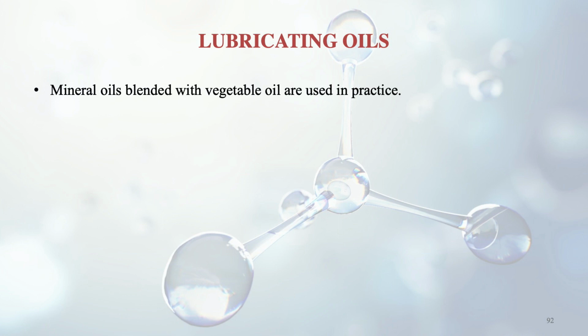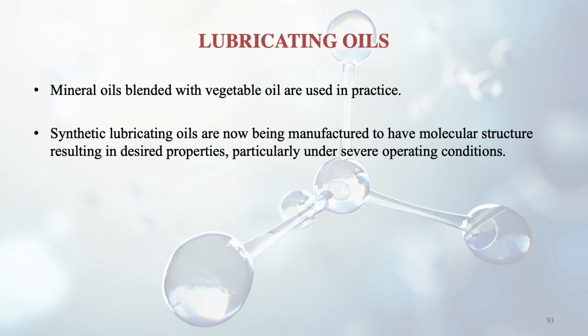Mineral oils blended with vegetable oils are generally used in practice. So we are using the combination of vegetable and mineral oil. And nowadays there are synthetic lubricating oils also, and they are manufactured for special purposes by bringing about change in the molecular structure. Special purposes are like under severe operating conditions, again temperature and pressure conditions. So there are further subdivisions also in case of this